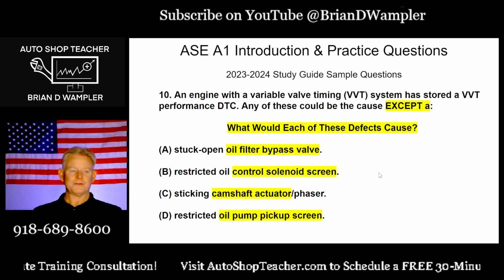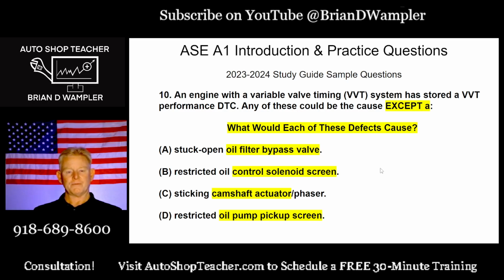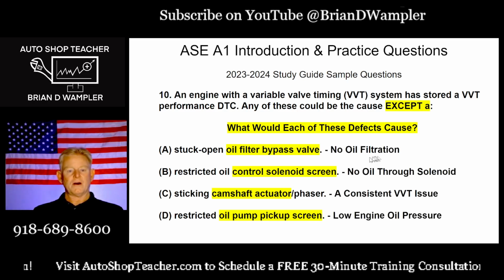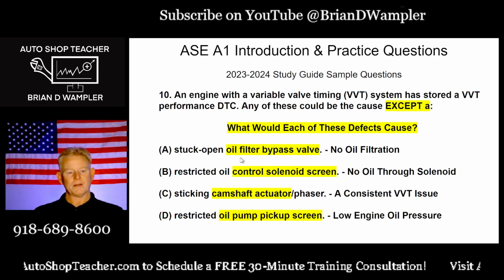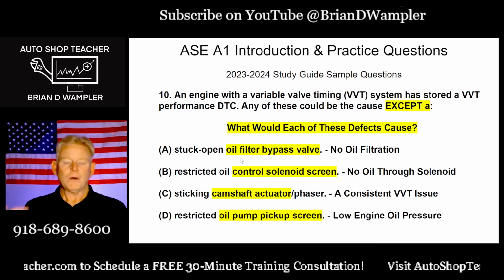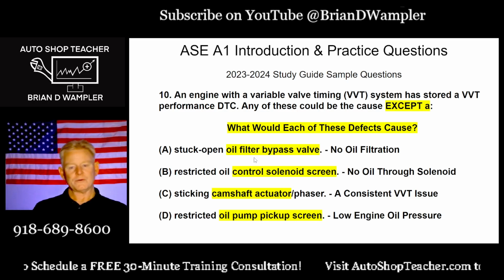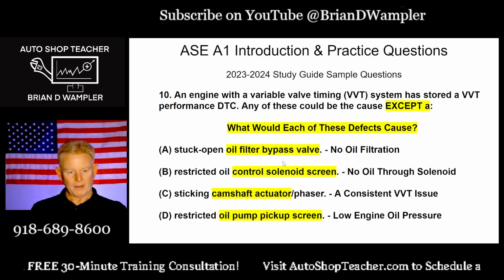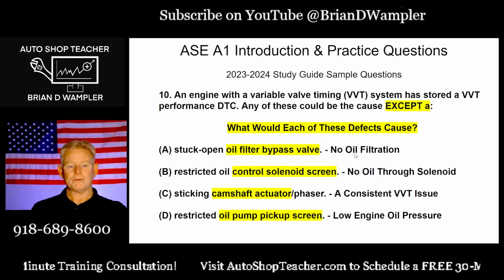But I'm not going to go into describing what a whole variable valve timing system is for this intro video, okay? So A is going to cause no oil filtration. Because remember, and I already pointed it out, we're talking about the oil filter bypass. Oil filter bypass opens when there's too much restriction in the oil filter, and so it allows oil to still circulate throughout the engine by bypassing the filter. It's a very bad condition, but it's going to cause no oil filtration.